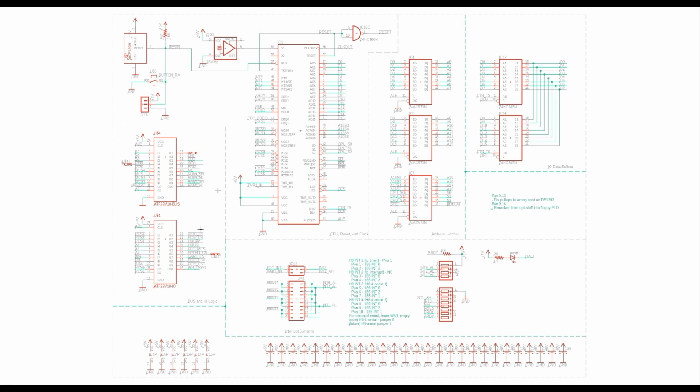It handles all that. The other one here called I/O handles most of our I/O selection logic. So it's got PCS 4, 5, 6, as well as 0 and 1. Those handle various I/O selects out of the CPU. You've got A4, 5, and 6, which are some addressing bits, memory write, memory read. And out of it, we will get the chip selects for the IDE device.